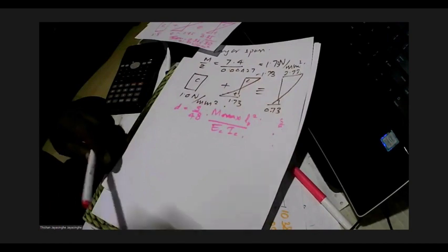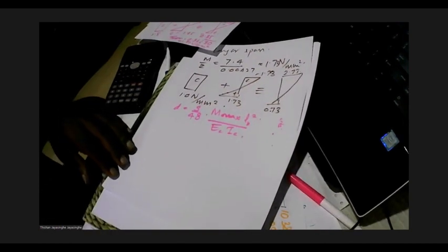Right. So, there's one example given in the notes, so we can go through the example as well. So, what is the deflection? If it is a two-way span slab, the shortest span direction will govern the deflection.